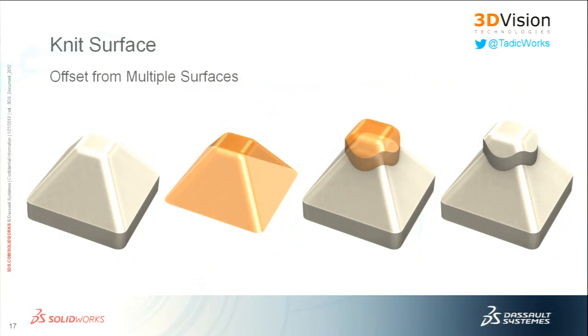When you did that wrap feature, did that just bring the sketch out to the cylinder with no thickness to the sketch? Well, there are actually three options to that wrap feature. I could either emboss, so extrude radially from that surface, normal to it. Deboss, so cut away material, normal to that curved surface.